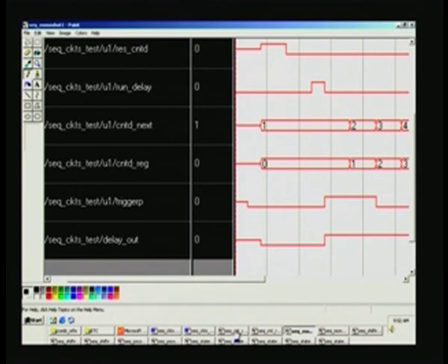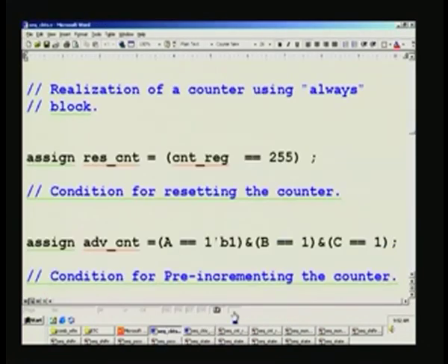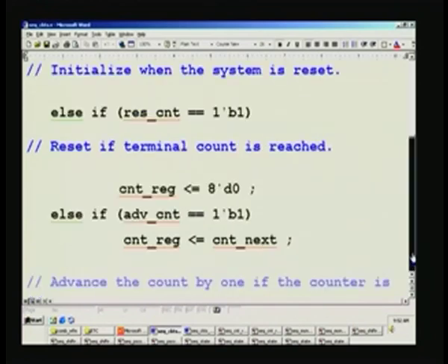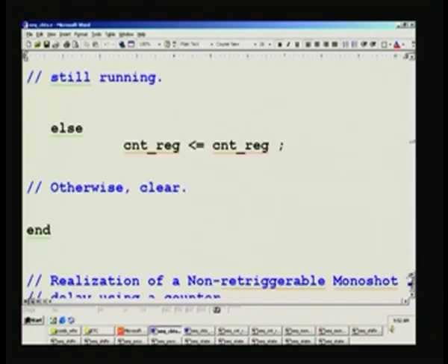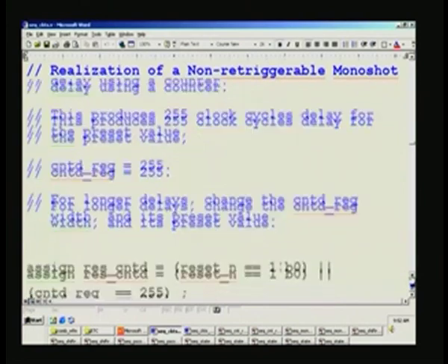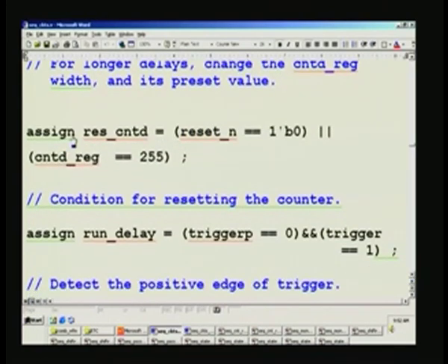So, if you look at the code for this, here we have combined two resets into one statement, that is power on reset here and also counter D being equal to 255. And when any of this happens, this is an OR here, so this will go high.